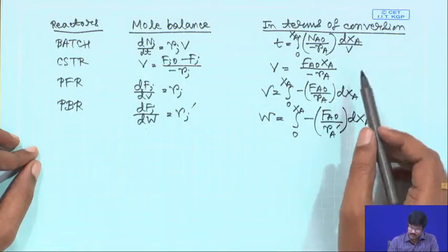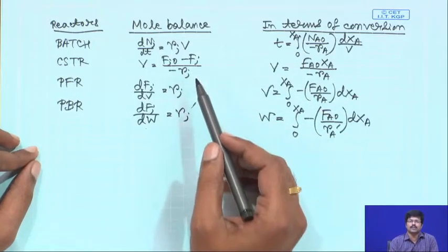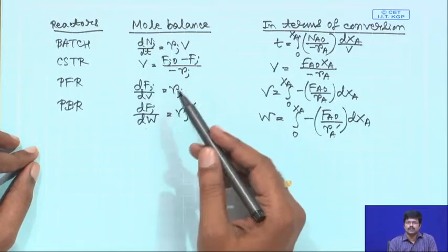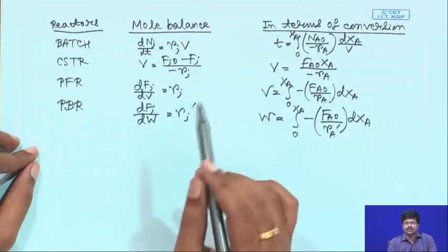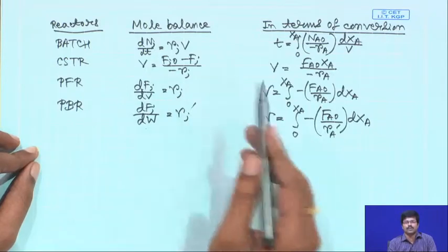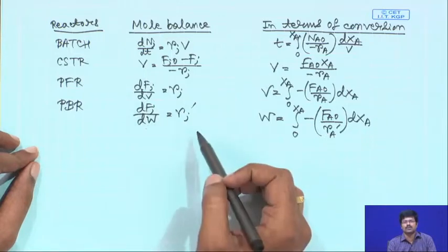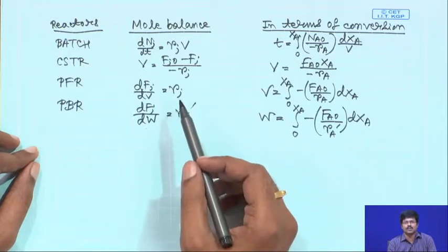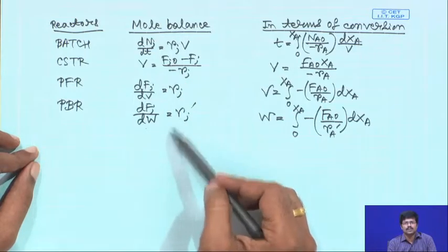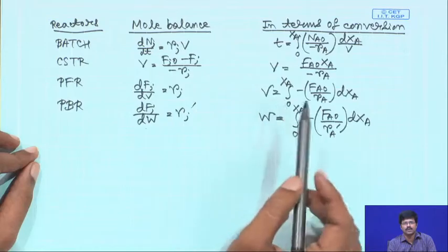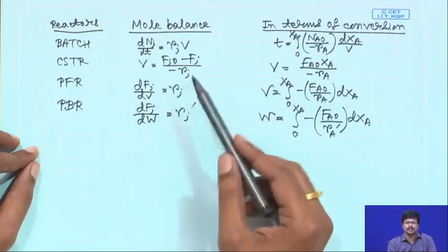And when we derived these expressions, we started from the expression of rate. So, the rate as a function of the concentration of different species, and then we expressed the concentrations of different species in terms of the conversion, the so called stoichiometric table, and then we combine these two, the rate law and stoichiometric table, in order to get a final expression of the rate in terms of the conversion for the reaction. And since the rate appears in all the design equations, then you replace the rate with that particular expression and you get your final expressions. We discussed these things in detail in the last week.